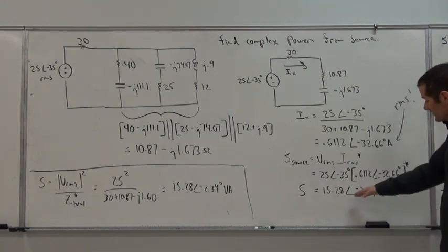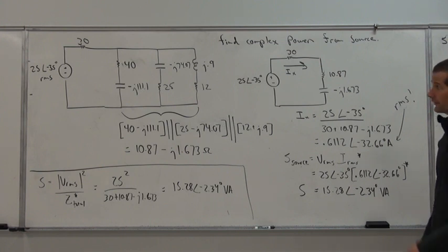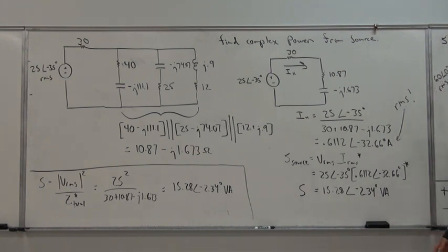And guys, what this is really indicative of, considering the type of system we are looking at here, is that if we consider that this is mostly a capacitive system, this current is in fact leading that voltage for sure. Definitely leading that voltage, therefore rendering that type of phase difference in which the current's phase angle is above the voltage's phase angle.